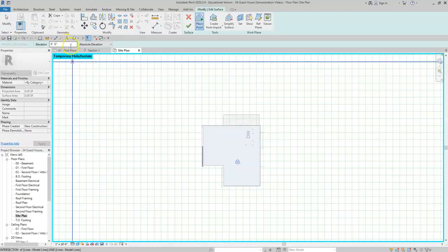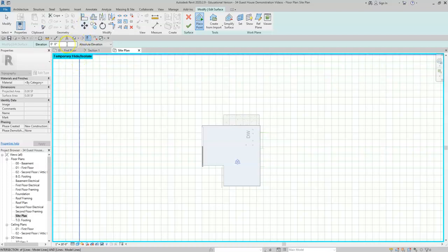And when we have a triangle, 3 points, land will connect underneath those 3 points. And we can click multiple points across the whole site. So I'm going to show you how to do that. Remember, we made our first concrete slab at -1 inch. That was in the first video. And we're going to place our soil a little bit below that, but not much. Our outside slabs are 4 inches below. So we can make a plot point no higher than, let's say, 5 inches below 0. So let's go ahead and do that. Let's make our first point at -5 inches.